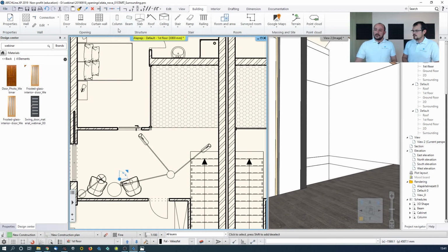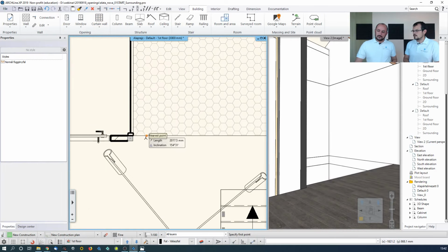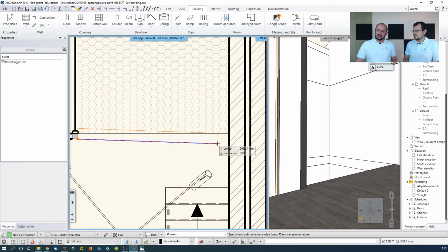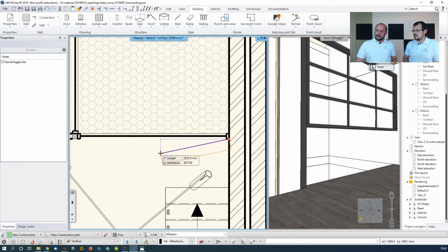But once you go to the commands, you will be able to find the one that you would like to create. There is a curtain wall tool with a curtain wall by 2 points, a corner window, we will talk about that later, and reshape a curtain wall. So if you simply would like to design one, you go with the first one and it behaves like drawing a wall. Oh, so it's the same tool set, it just looks different.